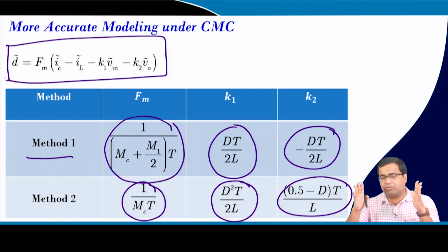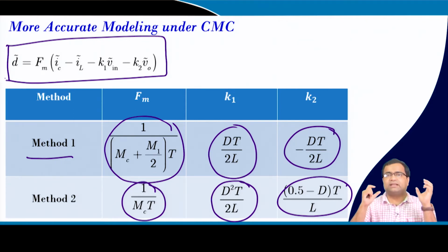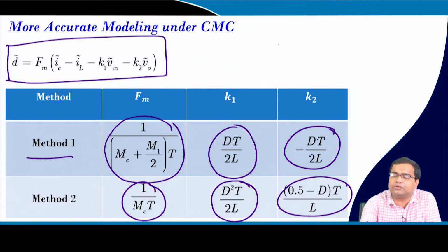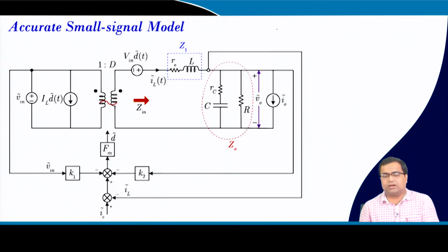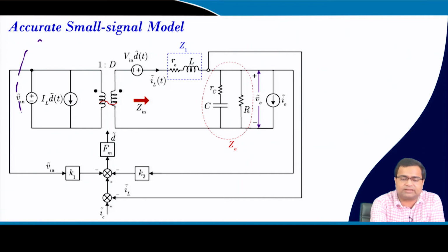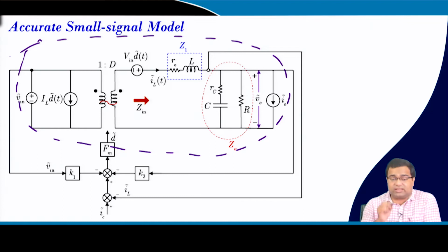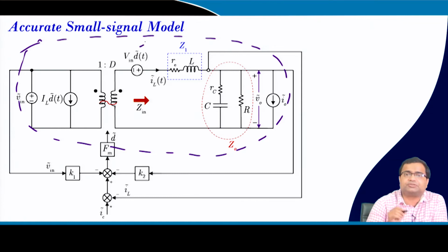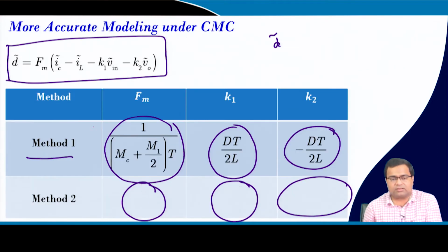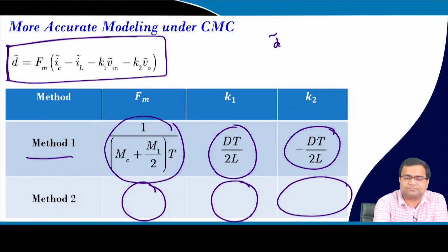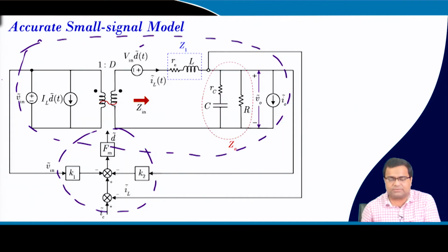That means, if we recall that when we derived the AC equivalent circuit using either the average switch model or circuit averaging technique, then in the AC equivalent circuit there was an open loop duty ratio perturbation, right. So, now if I am going back, this is my AC equivalent circuit that we have discussed earlier. So, in this circuit, the duty ratio perturbation is the one which is coming from the closed loop, and this expression we have got from this expression.